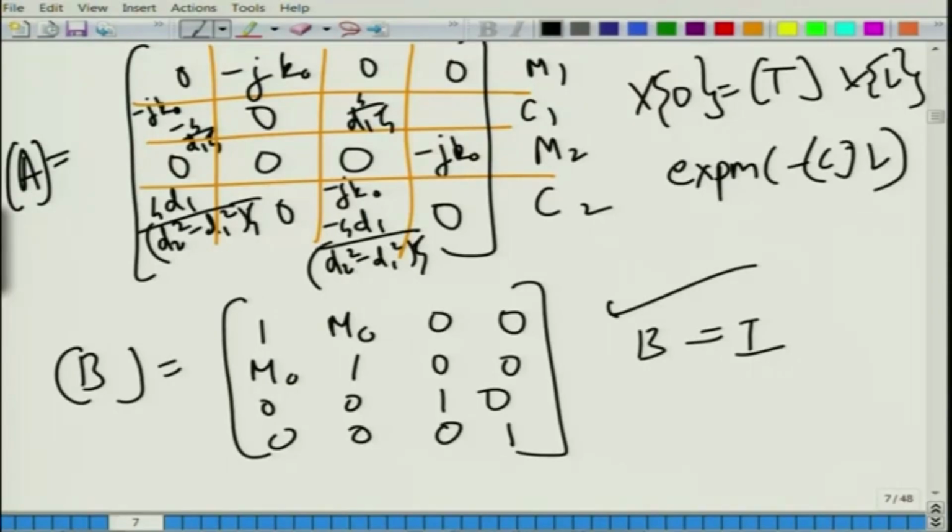Once we know the overlapping perforate length L, the diameter of the perforate pipe and of the annular cavity D2, and the frequency at which we are solving the perforate model, we can easily put in the expressions and go about it.